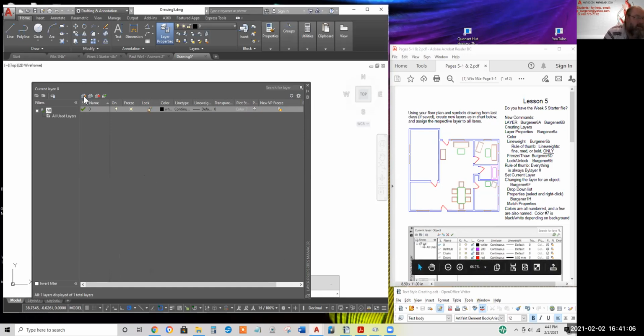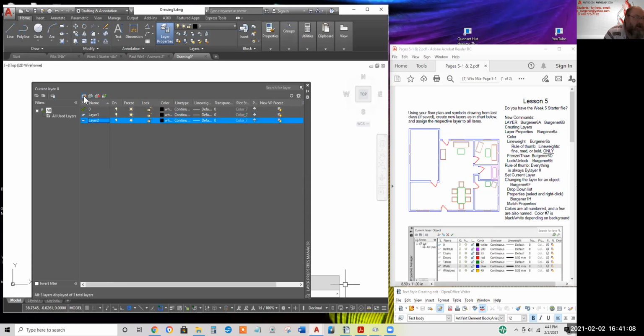Just click on this starburst, and each time you click on it, it creates a default named layer, 1, 2, 3, because what else does it know how to name them? You can rename them as you create them. Notice it sets up like a typical Microsoft renaming. You got the blue box. So go ahead and type, say, doors.